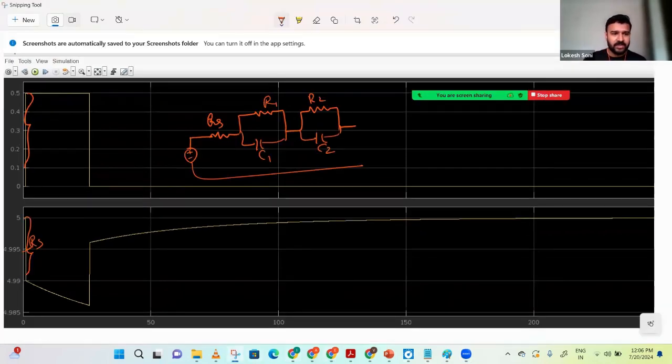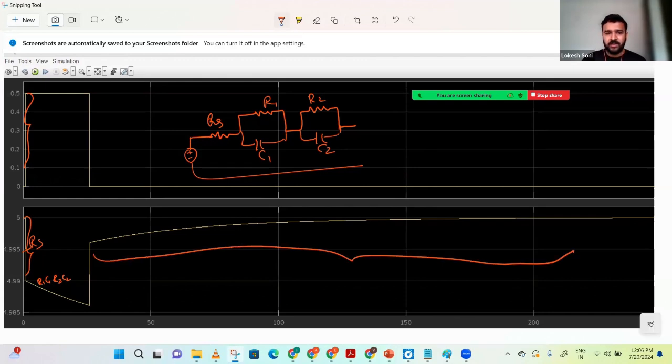Yeah. So this sudden drop is because of RS. Then this part is because of R1 C1 and R2 C2. The better place to understand this behavior is this section, which is called the relaxation area. You see the voltage is relaxing over this much time. Even when the current is stopped at this point, it takes almost this much time for the voltage to relax. If we decode it properly, you would find two dynamics: a faster dynamics, from R1 C1, and a slower dynamics, from R2 C2.